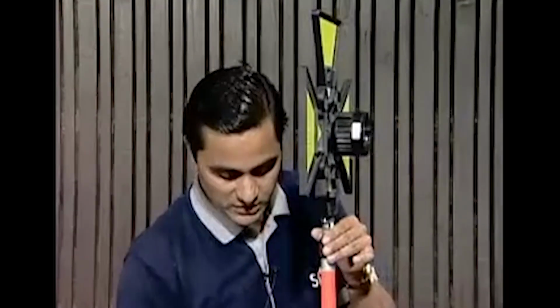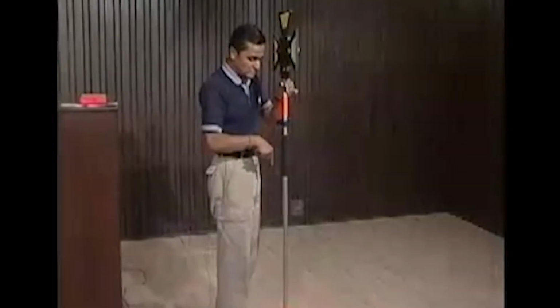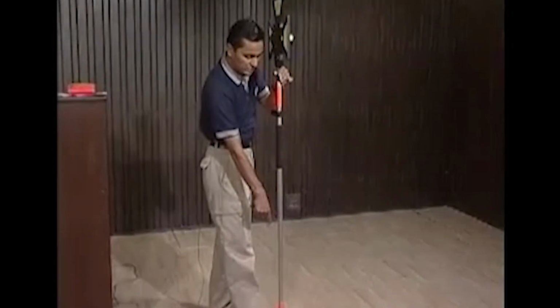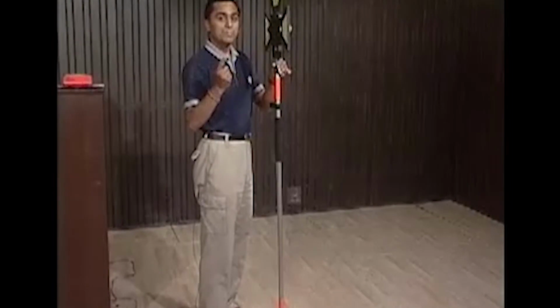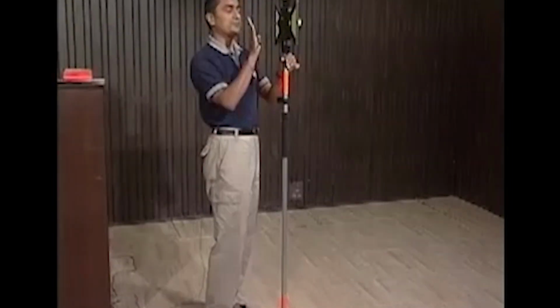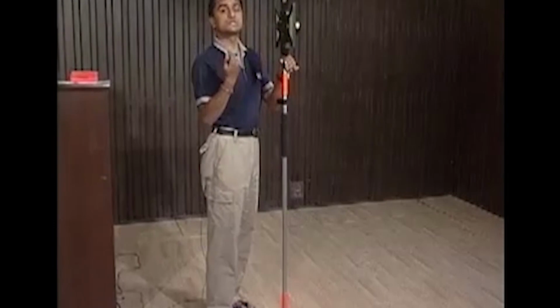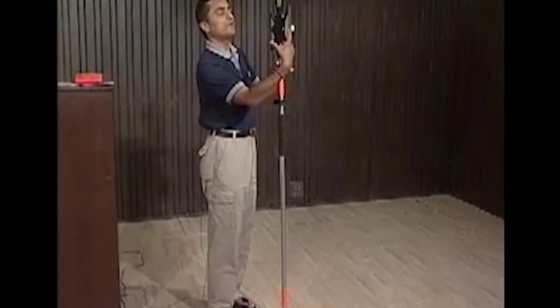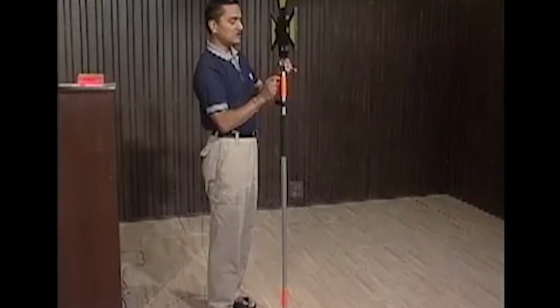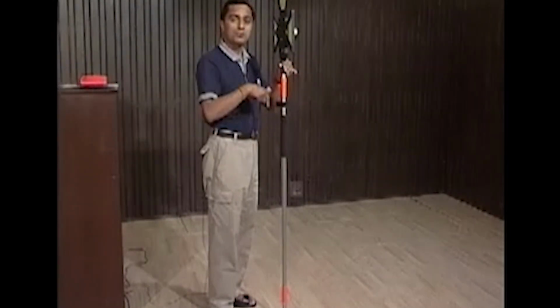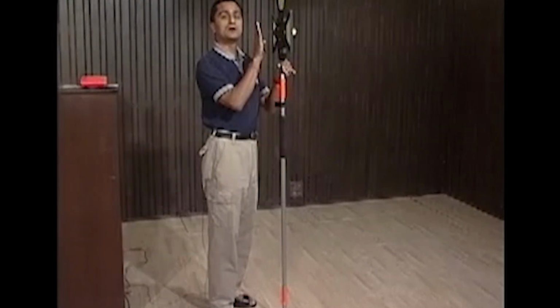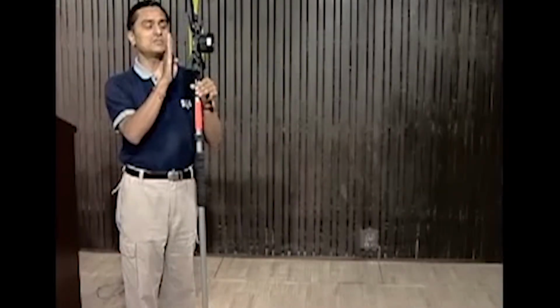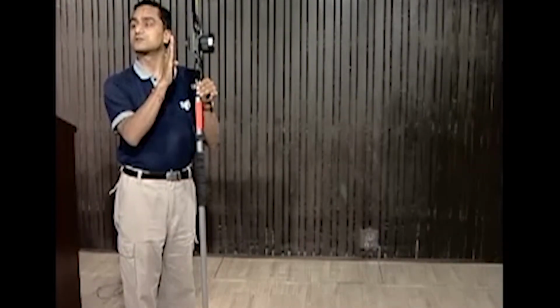Now there in the ground, I am measuring the distance from this point where this rod is, or where the center of the rod is. So for this center of the rod there in the ground, I want to measure the distance from that point there in the ground, but my laser is equivalent to be reflecting from here. So there is a discrepancy, this discrepancy of around this amount. From the center of this rod, which you can see there in the ground where I have put it, to this point, we need to apply a correction again. Now this correction we say target correction.